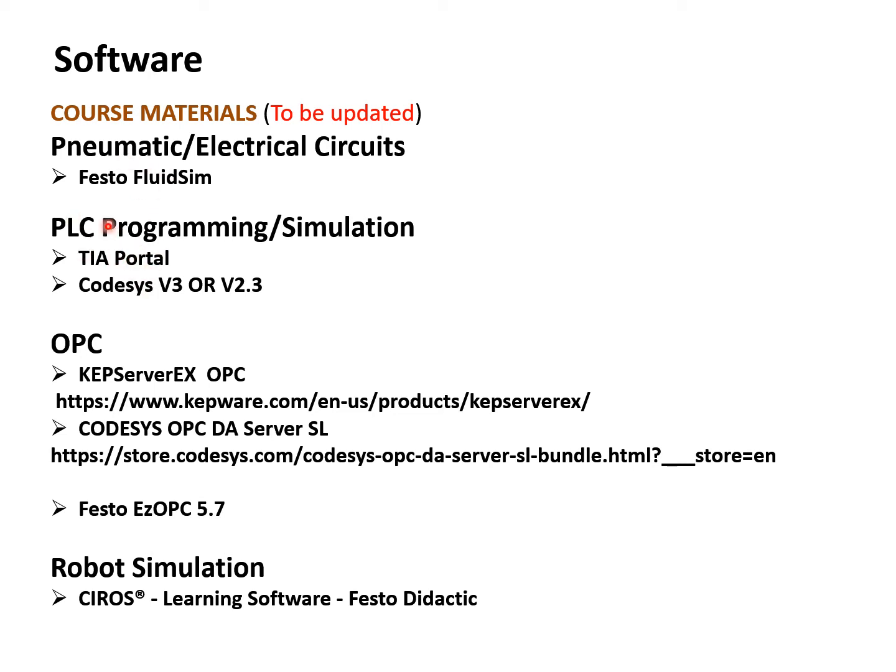You could use OPC to connect these PLC programming software to MATLAB Simulink. And you could use OPC to connect PLC programming in CODESYS or TIA to Festo FluidSIM. Okay, and we have to have an OPC software.